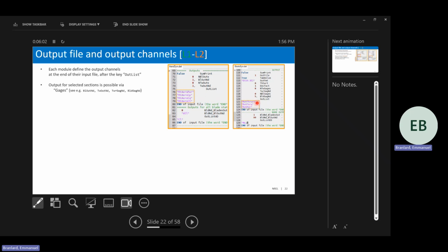So like the rotor thrust, the rotor power of ElastoDyn is different from the rotor power from AeroDyn, because AeroDyn only knows about aerodynamics and doesn't know about inertial loads and gravity. That's a common misconception when users start using OpenFAST. And as I mentioned, we have these nodal outputs. We'll get through the examples. That gives you, for instance, the lift coefficient at every radial location along your blade. That's for AeroDyn. For ElastoDyn, you can have, for instance, the bending moments along the Y direction and L_y at different sections along your blade, tower, things like this.